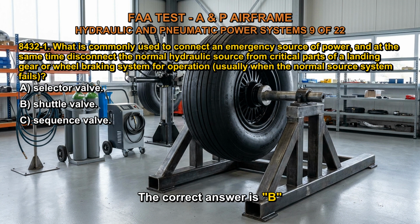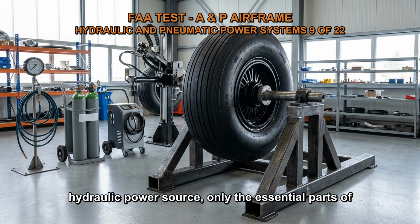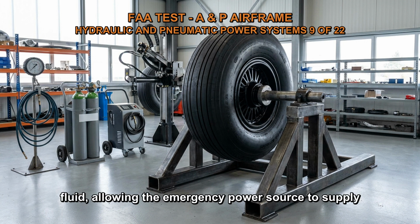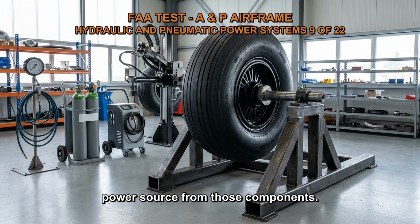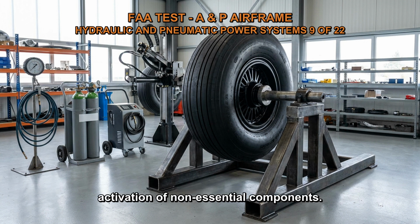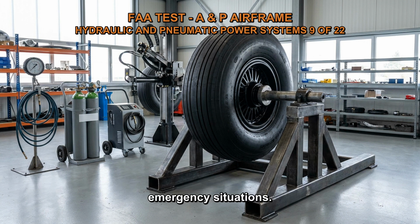The correct answer is B. A shuttle valve is a component used in certain systems to ensure that in case of an emergency requiring the use of an alternate hydraulic power source, only the essential parts of the system are activated. It acts as a selective pathway for hydraulic fluid, allowing the emergency power source to supply fluid to specific components while isolating the normal power source from those components. This ensures that critical functions can still be performed using the emergency power while preventing unnecessary activation of non-essential components. The shuttle valve helps optimize the use of emergency hydraulic power and maintains system functionality during emergency situations.